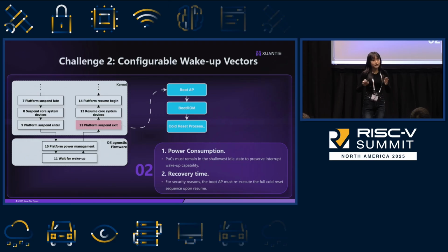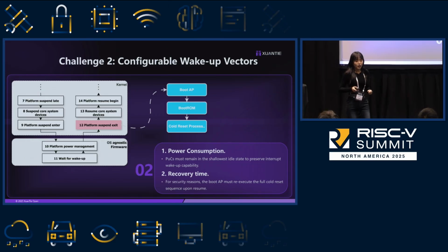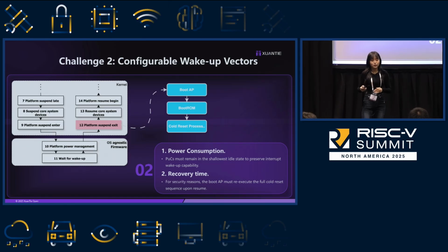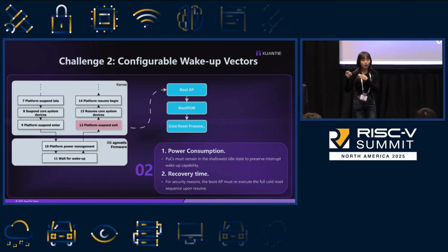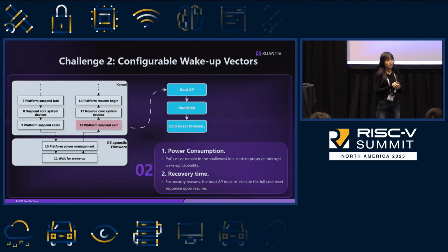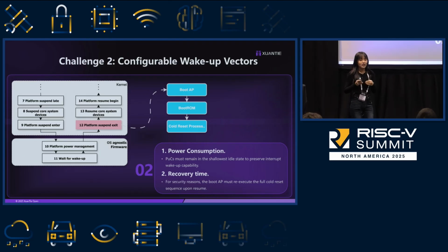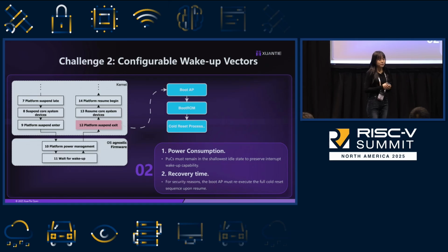And another thing, for the boot core: the boot core has to stay alive long enough to notify the system controller. And after the system controller resumes back to the OSPM, it will release the boot core, right? But due to the security constraints, the boot core has to reset from a fixed address. This hardware design makes no difference between the cold boot and the system resume.